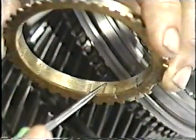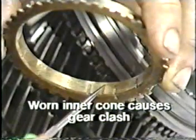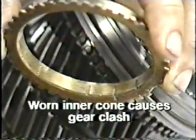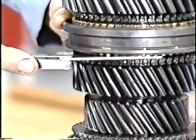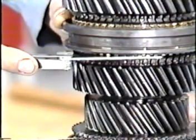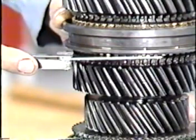If the inner gripping surface of the synchronizer ring is worn, it won't bring the drive gear up to the same rotational speed as the sleeve, and gear clash will occur. You don't have to disassemble a synchronizer to check for synchro ring wear. You can simply measure the clearance between the synchronizer ring and the drive gear when they're firmly in contact with one another. A measurement less than that listed in the shop manual is a sign of excessive wear.